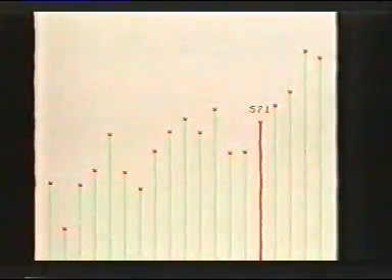So the accuracy of the representation of the analog input would be very dependent upon the size of those time slices. You can see it on that original graph. When I was moving it very slowly, it gets a fair representation of moving it. When I moved it very quickly, obviously I was moving it further in the time slice that was allowed. That's the major problem with analog devices. You must sample very frequently if you're to get an accurate representation. So 2 analog inputs there we've dealt with.